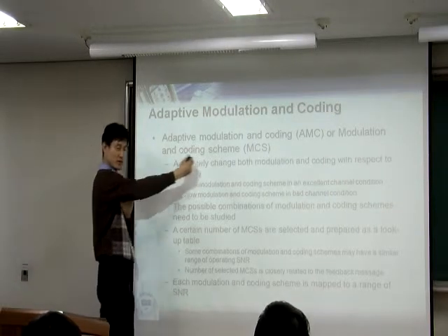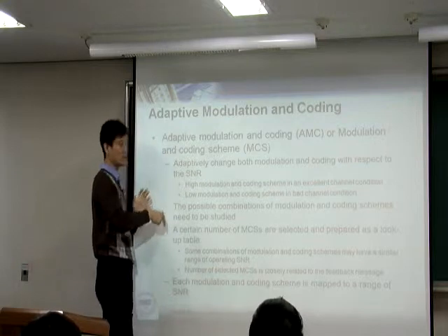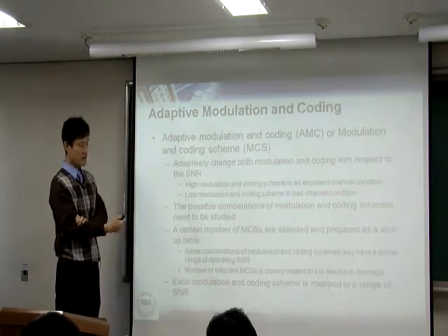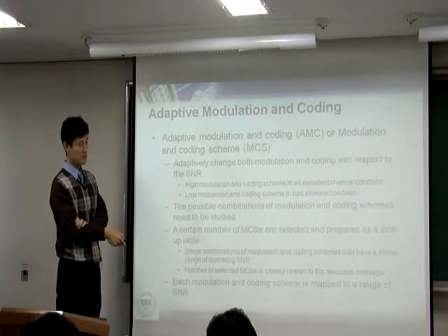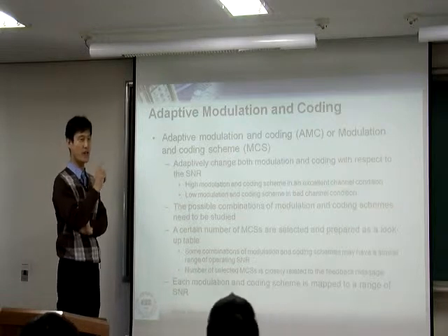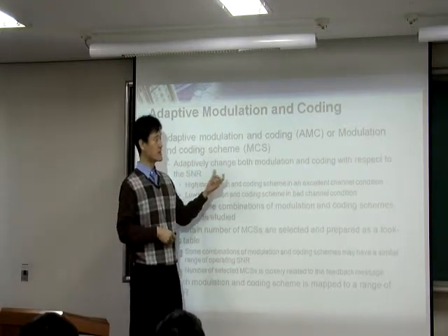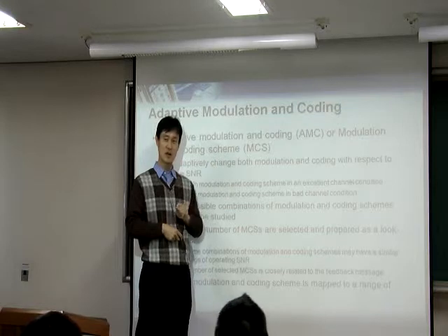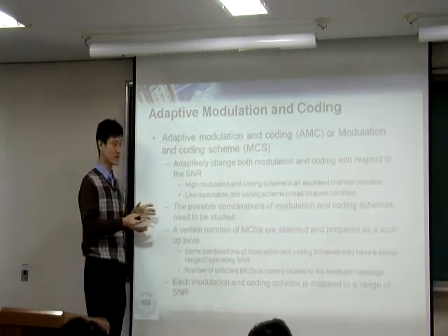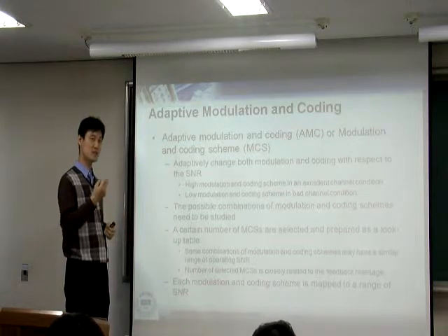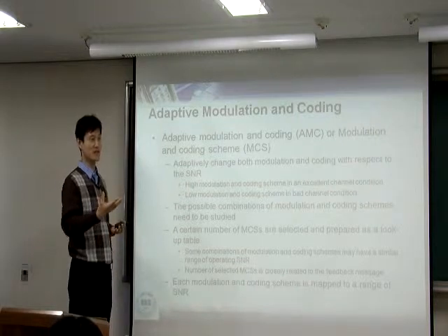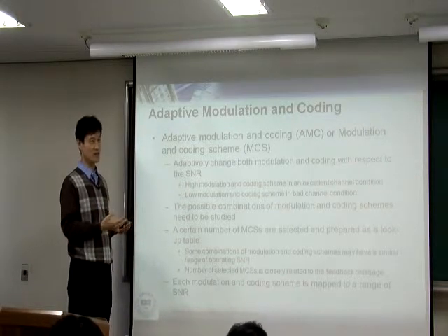We have to feed back the channel condition. That way we change it, right? But in practical systems, the feedback message can never contain your H hat. H hat is your actual estimated channel gain, which is going to be a complex value. That cannot be transmitted, right? In a practical system, what is actually transmitted is just bits, typically just 2 bits or 3 bits. Even 3 bits is really large.